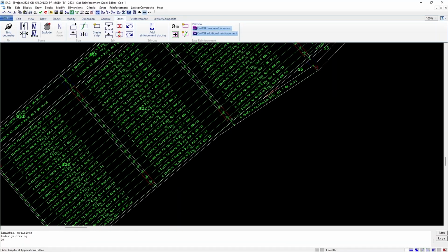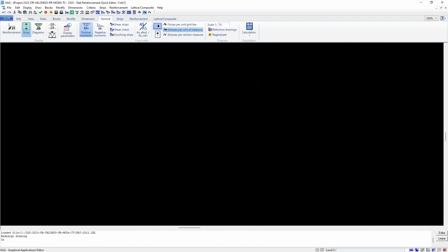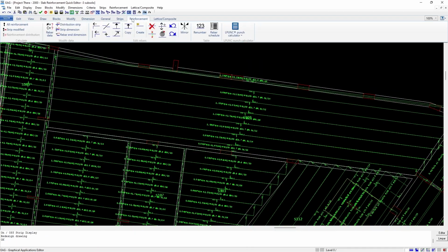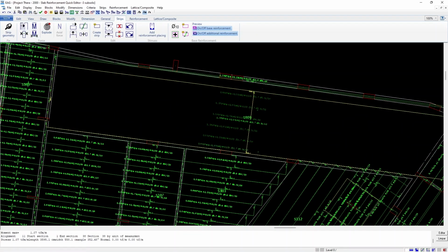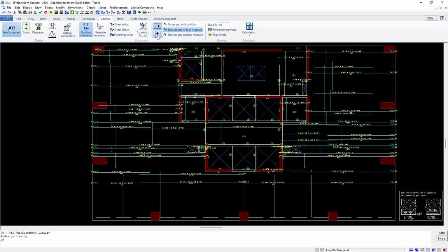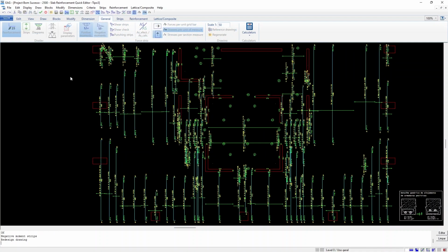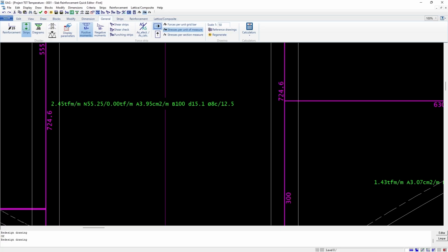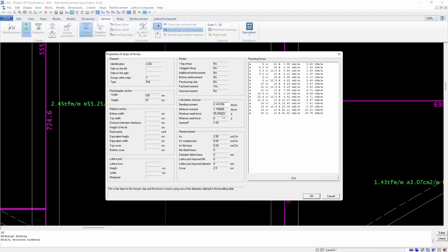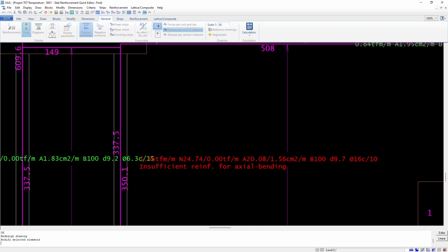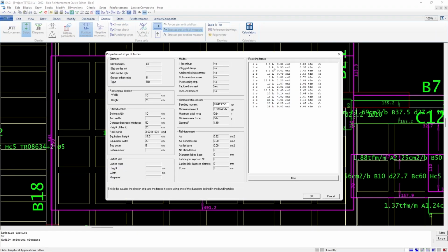These strips are automatically homogenized and grouped to achieve optimized detailing. In the editor, the homogenization of the force strips can be edited and adjusted interactively. Based on the force strips, longitudinal reinforcement for pure bending is designed in the main and secondary directions of the slabs. In floors where axial forces are significant, such as when slabs are pre-stressed or subject to temperature effect, shrinkage, or inclined geometry, the slabs are designed for combined axial force and moment.